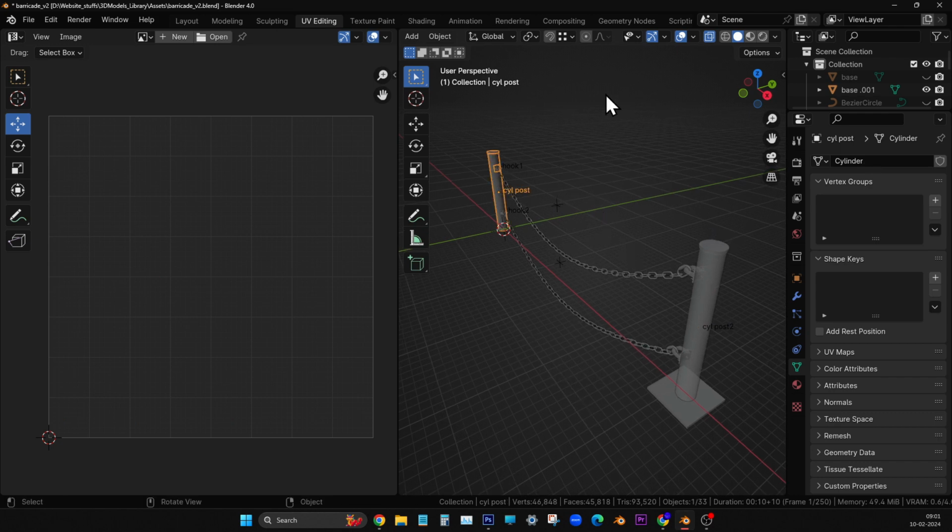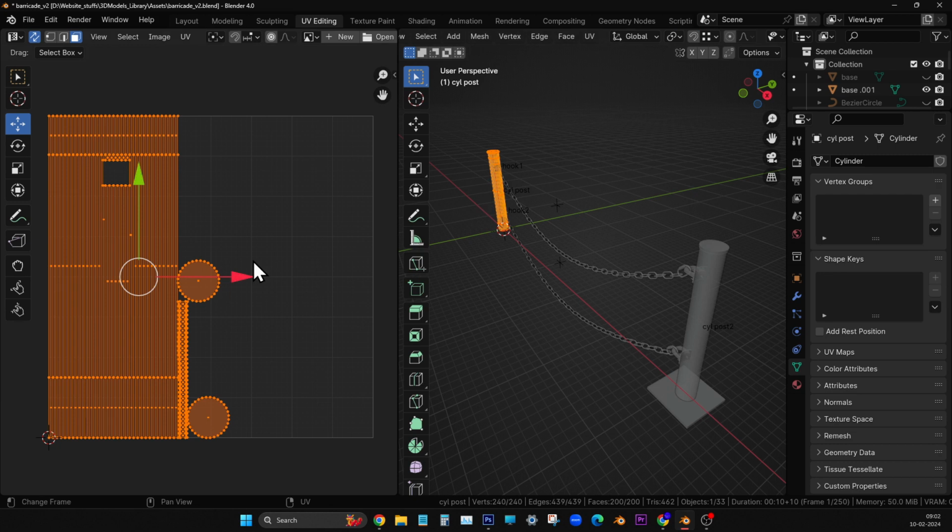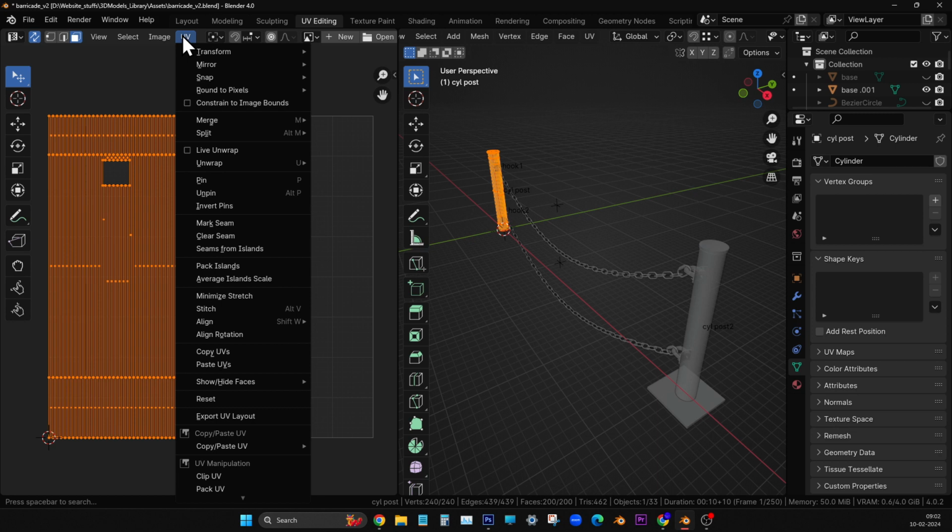Right now, I'll go to edit mode and then go to tweak. I don't want this gizmo to obstruct my view, so every time I'm going to default cursor mode, which in Blender they call tweak. Now I have selected my mesh. It should be in selection, yellow color, active selection. Only then we have to go on. Only after that we have to go to UV snapshot.